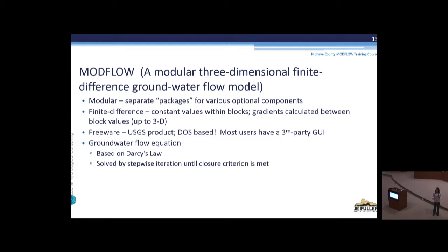I mean, life isn't like that. The world's not like that. But modeling is all about approximation and assumptions and time. So when you look at properties in the groundwater model over the kinds of time periods that we're talking about, generally months to years to decades, a lot of these little details that we're concerned about on the surface don't really matter. And that's a really key thing to understand when you start modeling, is what's important and what isn't to resolve.